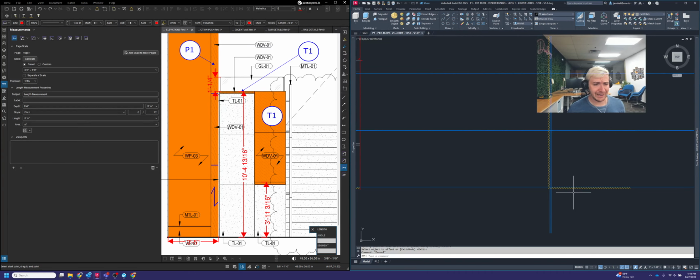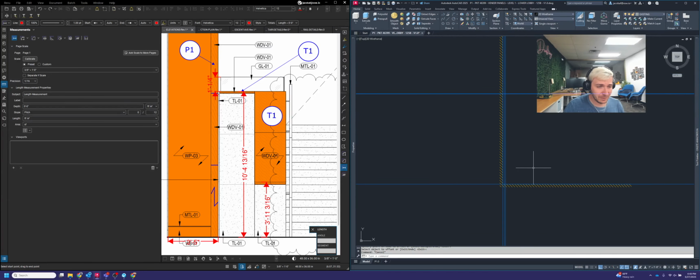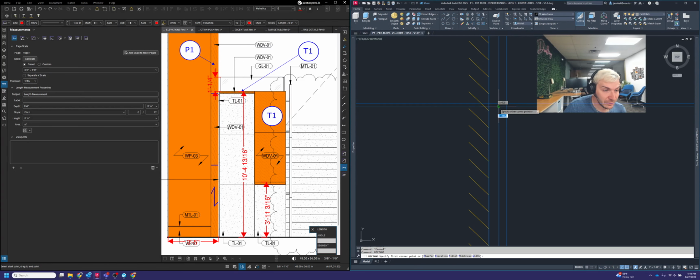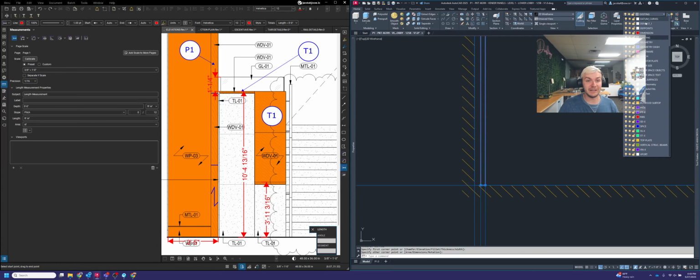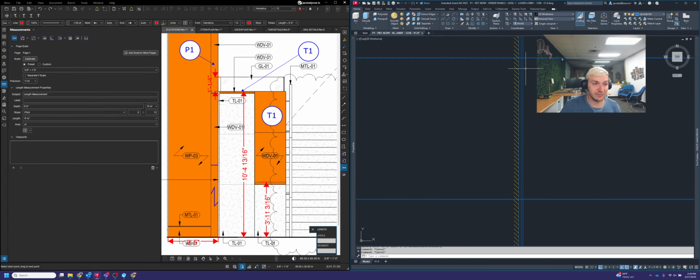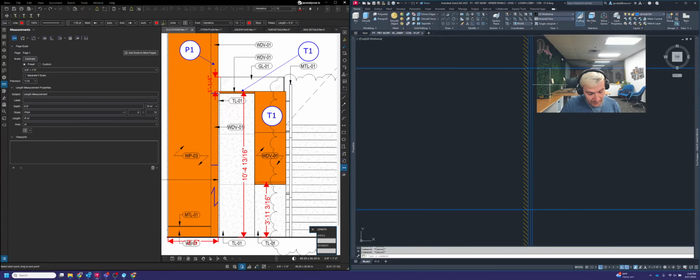We're going to go ahead and draw in rectangles to represent the panels now. So we're going to type in RECT, rectangle, and we are going to drop in a rectangle from there to there. Oh, see, I'm on the wrong layer. Beginner's mistake. I should be on geometry here. Let's make sure that my current layer is set to geometry, so that way I'm not drawing these on the incorrect layer.